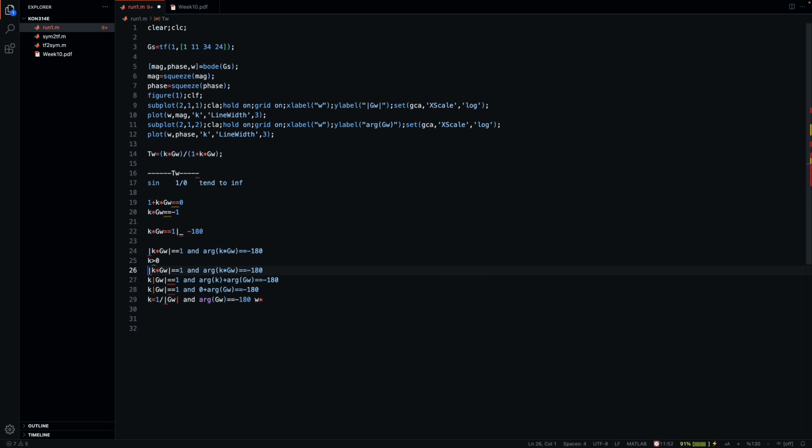Now we have an assumption up here. Let's have another assumption which goes like this. Let's assume that k is negative at this point, because as you know from the time domain methods, we have a positive root locus and a negative root locus. Therefore, we should consider the positive gains for once and the negative gains. So now I'm doing that. The same applies here. We will have the sum of arguments again.